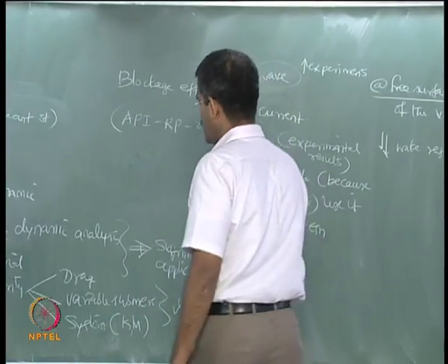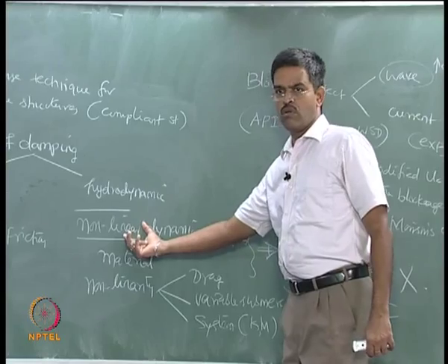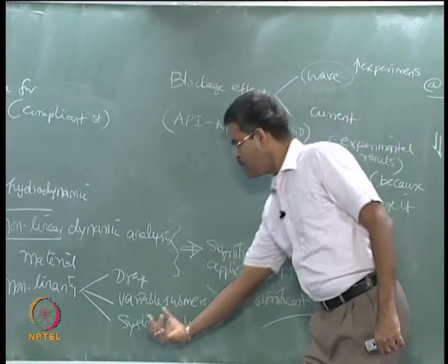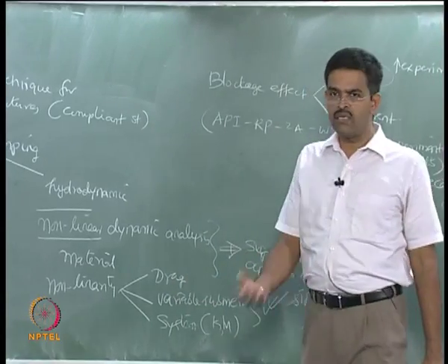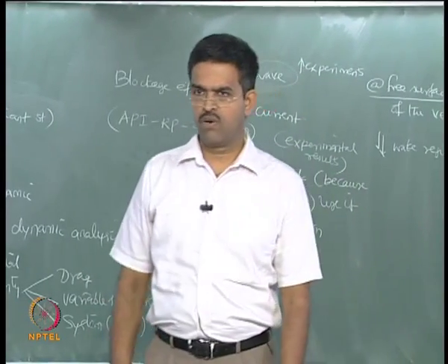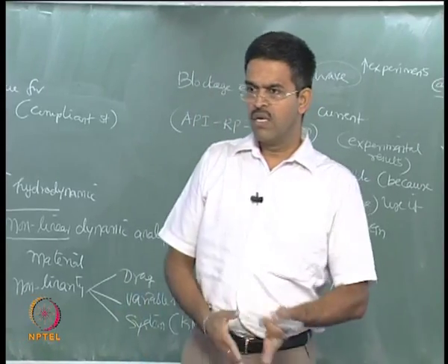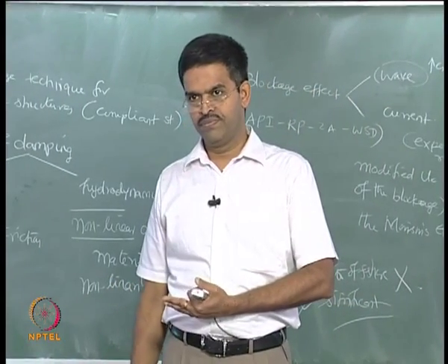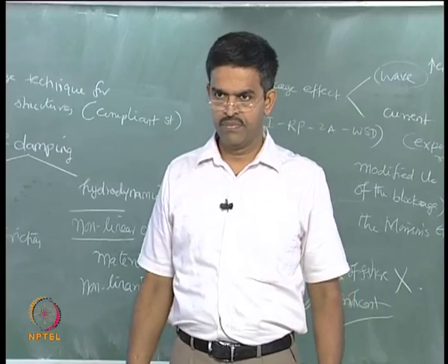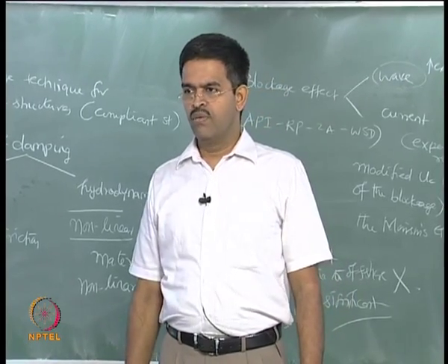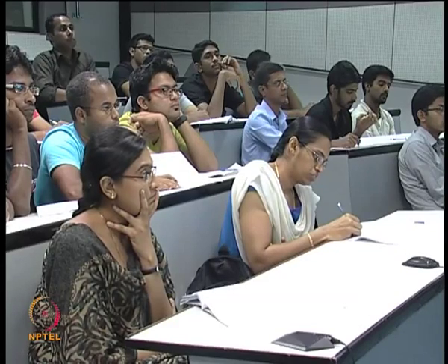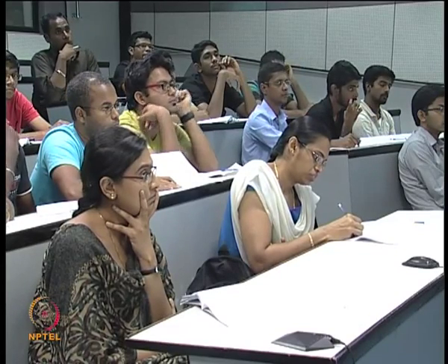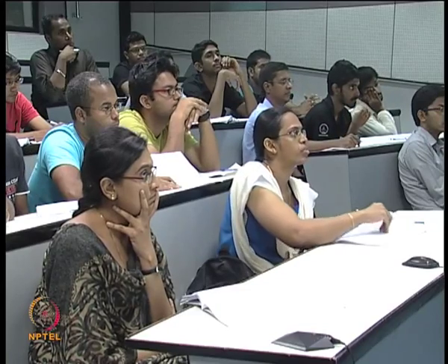Essentially, non-linearity plays an important role, majority from the form which is compliant or from the load, which is handled appropriately in the analysis, because people always find equivalent linearized drag instead of a non-linear drag. You can find literature where people use equivalent linearized drag instead of non-linear drag in the forcing function. So damping essentially comes from 2 sources, material and hydrodynamic.